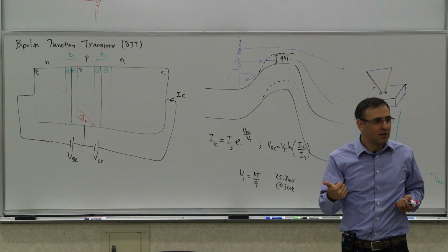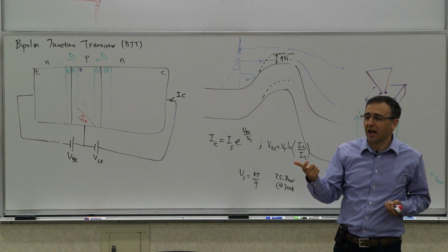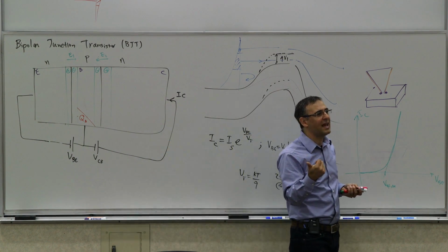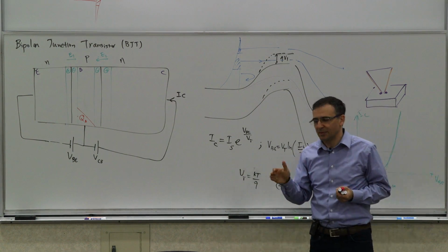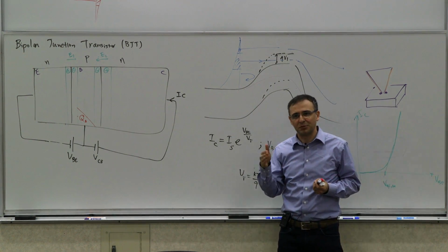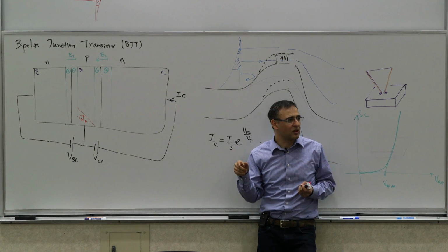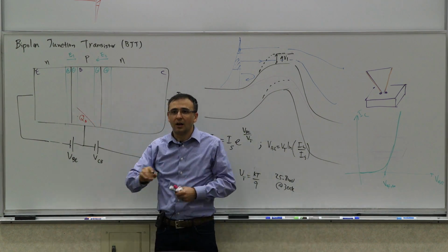There was mu. There was Q, electronic charge. It's kind of hard to change that. There's the mobility, which is again not an easy parameter to change. I mean, there are ways, but increasing it beyond a certain level is hard. And then there's n, the concentration of the charge carriers, right? In this case, it would be p because it's p-type.